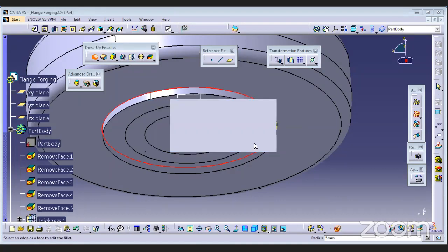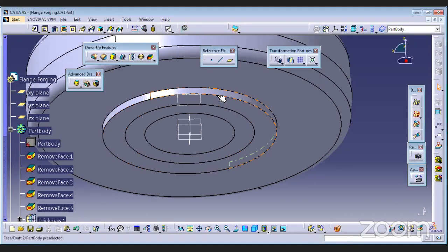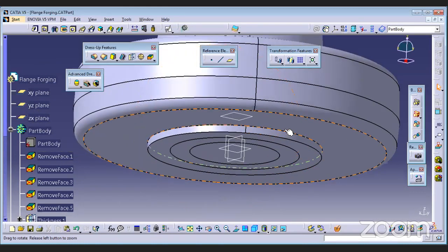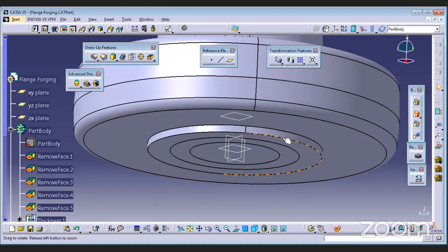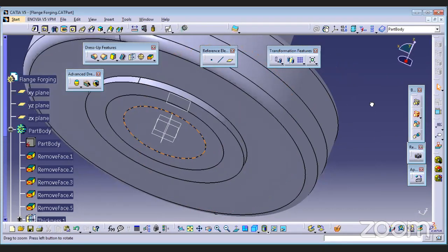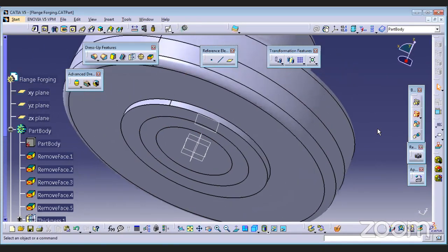Okay, if you know, fillet is a quarter circle, right? When we apply fillet here, the calculation behind that its section is a quarter circle. So we cannot fit a 5 mm radius fillet with a space of 4.32 or less than 5 mm gap. So here we need to use some different features of CATIA. One solution is there is fillet at this edge also. Okay.